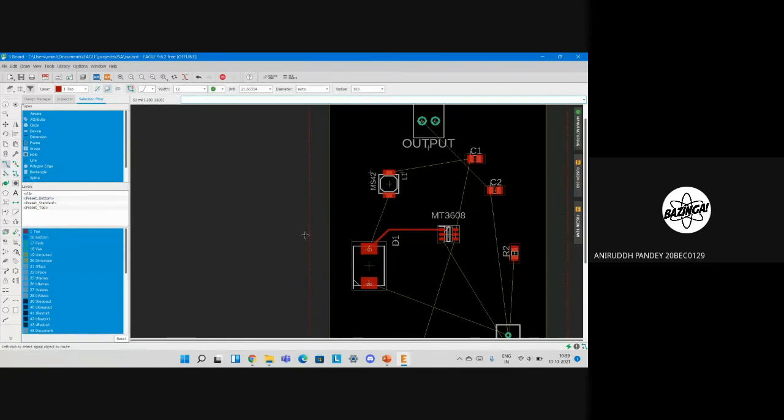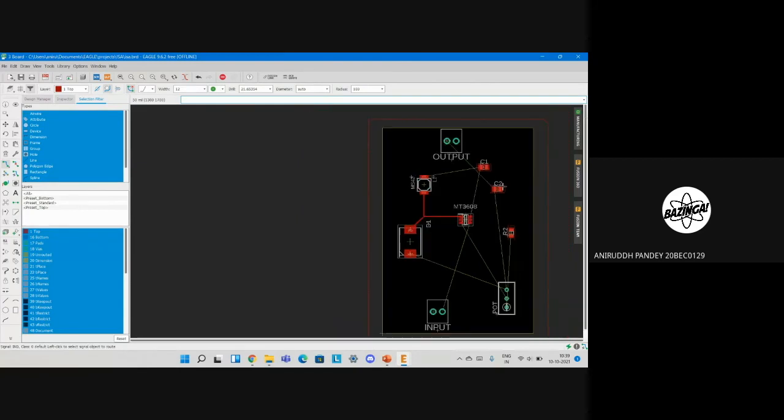I'll go again to the route, and this is connected to this part. So you can simply connect over here. Now 90-degree turns won't matter in this simple circuit, because there's not a lot of heat that is going to be dissipated on the turns. So you can make a 90-degree connection over here, but just keep it a habit to have 45-degree turns.